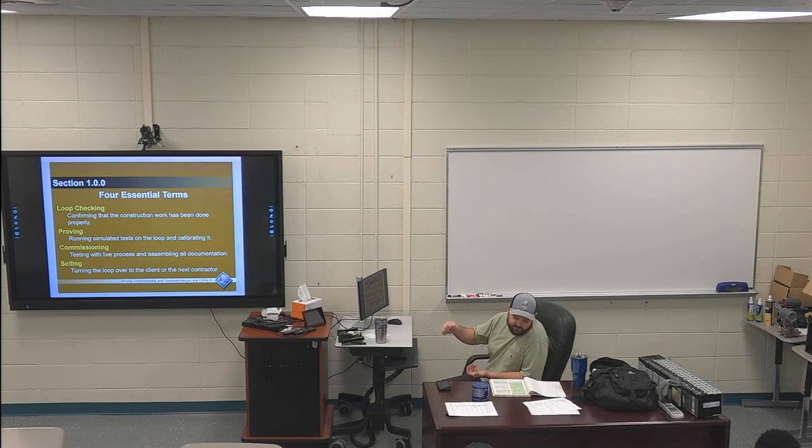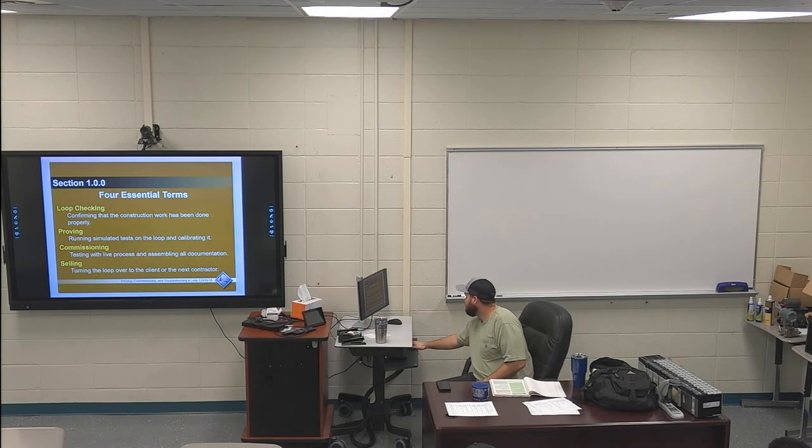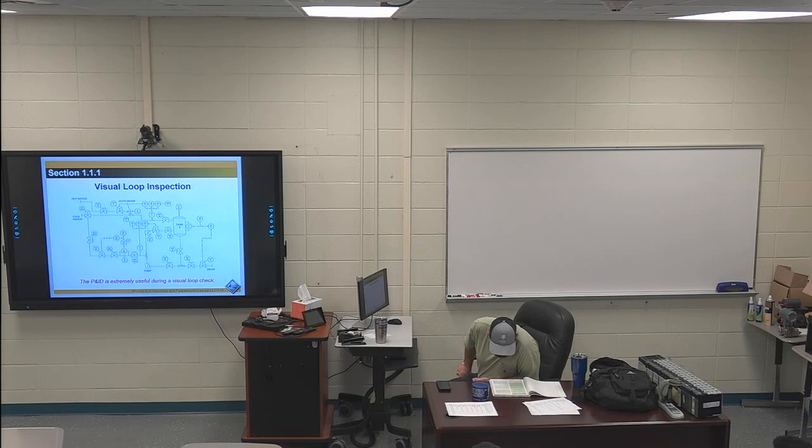Mechanical inspection, or this is in 110 loop inspection going on to 111 mechanical inspection. I got the second and third sentence highlighted, which is the last two sentences. The materials and components installed may also have been damaged during installation, or they may have arrived from the supplier in an inoperable or damaged condition. For these reasons, among others, it is necessary to verify the mechanical installation of all instrumentation loops before assuming they are ready for calibration or normal operations.